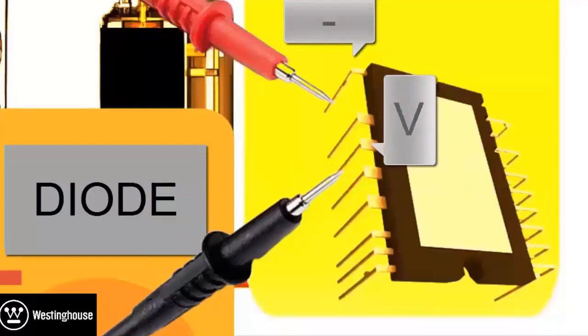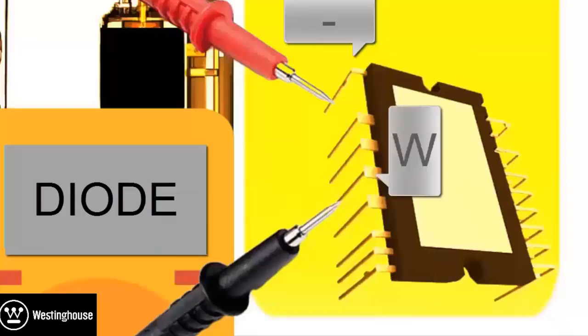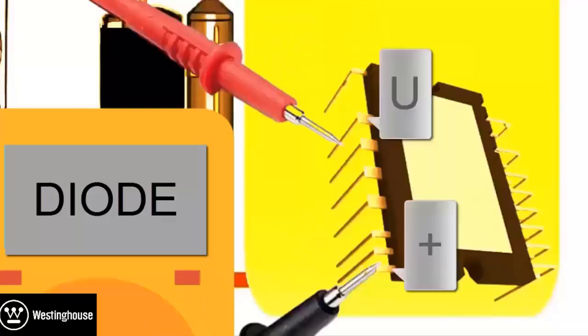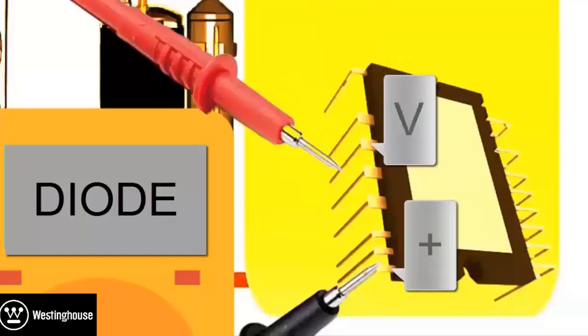Place the multimeter's red probe on the negative pin of the IPM module. Place the black probe on each of the U, V, and W pins. The measurements should be nearly identical across all tests. If there are significant differences, a fault is present.